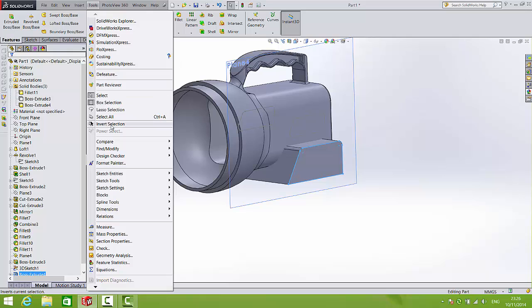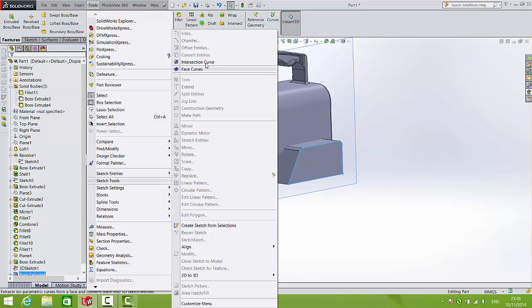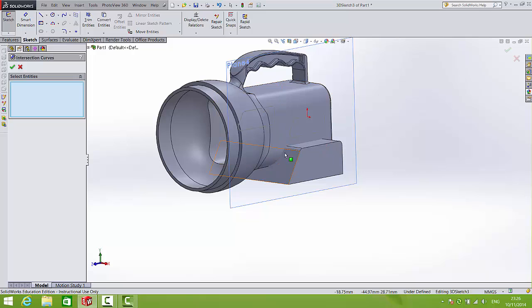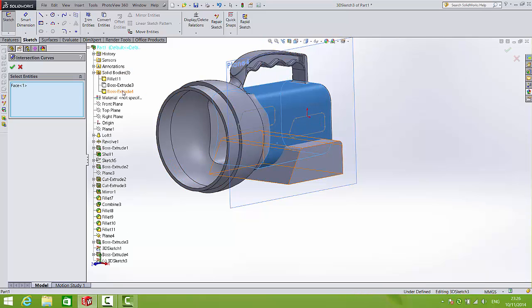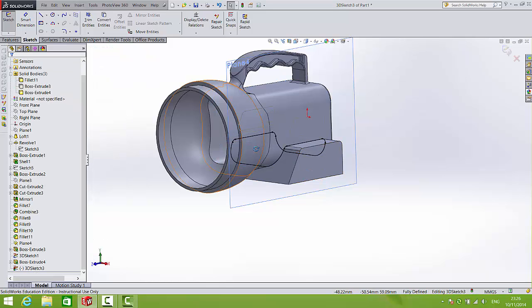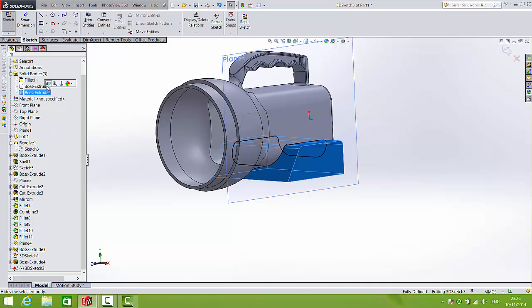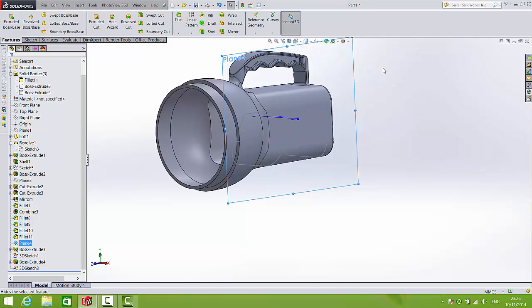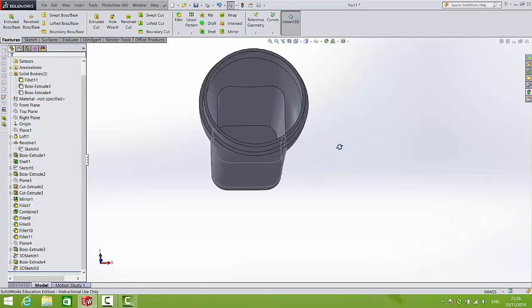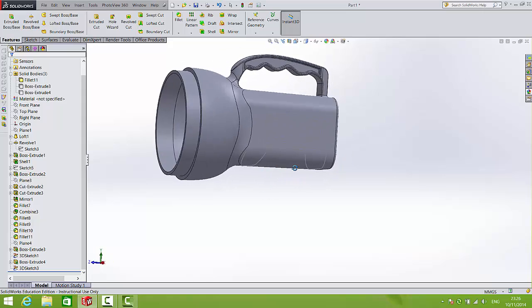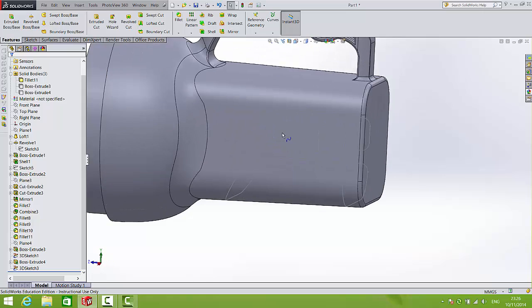model. So, Tools, Sketch Tools, Intersection Curve. We'll select the face and that final solid body. And you can see a much more complicated intersection curve is generated this time. And if I hide the plane in a moment, you should be able to see both of them at the bottom. So let's use those, and we're going to do a bit of surface modeling here.